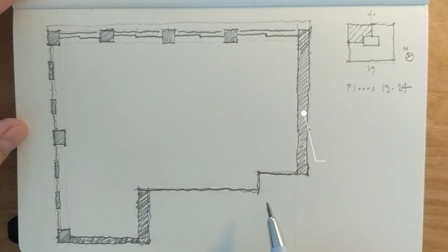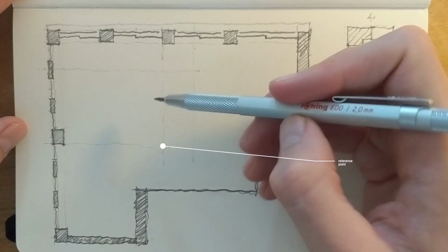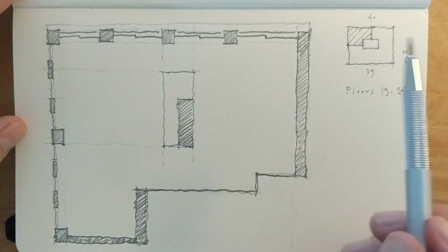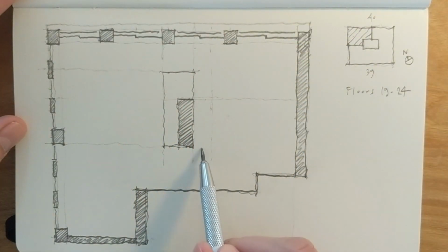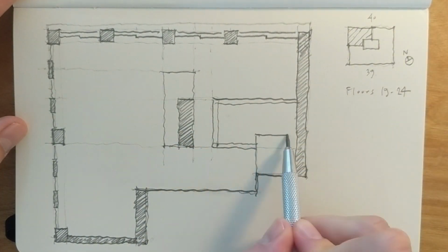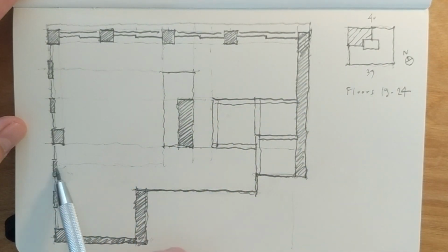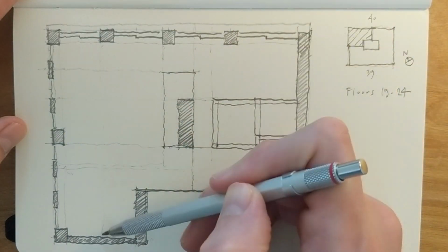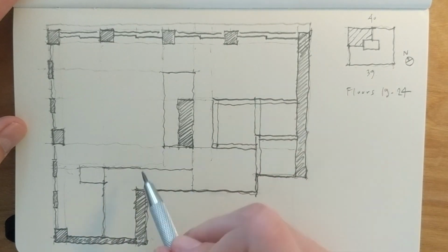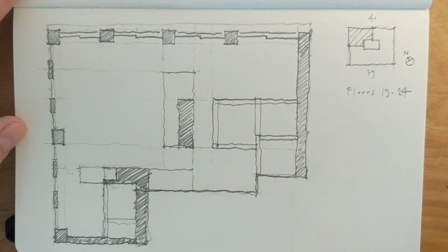Next, I can start setting up the interior walls. I can see that the architect has lined up some of these walls with the window openings, so I can establish a corner reference point and figure out wall locations from this corner. I use this technique of finding reference points to figure out the location of the kitchen and bedroom walls. Hatching in the walls and supports helps to graphically define them.